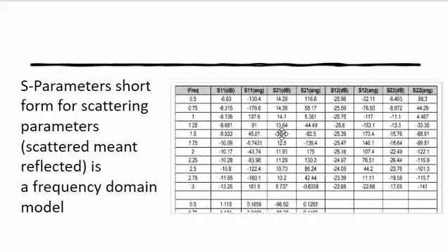Okay, so now S parameter models, if you see, this is a simple example of an S parameter model where at a specific frequency you have different parameters, and as seen in the table they are S11, S21 kind of, right? So these S parameter models, if you see by this table, these are actually frequency domain models. So you have various parameters mentioned at different frequencies, and these basically represent the actual performance of that particular structure for which we have the model, right?